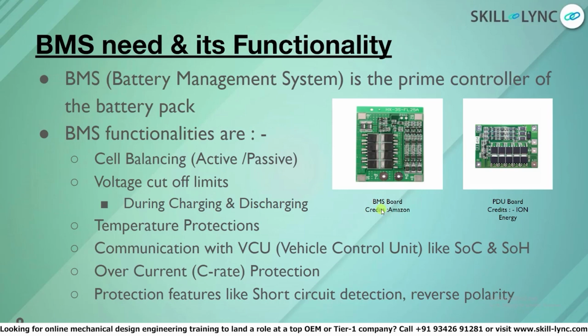Also, we have other safety features for the battery pack, such as temperature protection. That is, it will not allow the battery pack to operate above a certain temperature limit. And how is it done? This is all done through programming the BMS with the right values needed to give all these protections. The BMS is also the sole communication authority with the VCU, and it transfers parameters like SOC, SOH, all the error indications, and data like battery pack temperature and operating temperature, whether it is safe or not, etc.